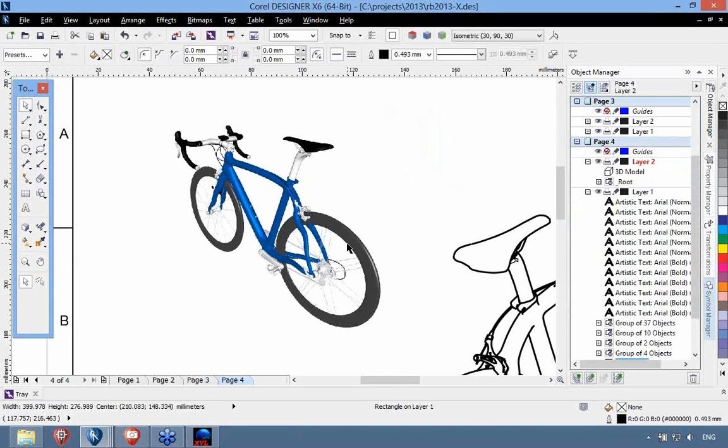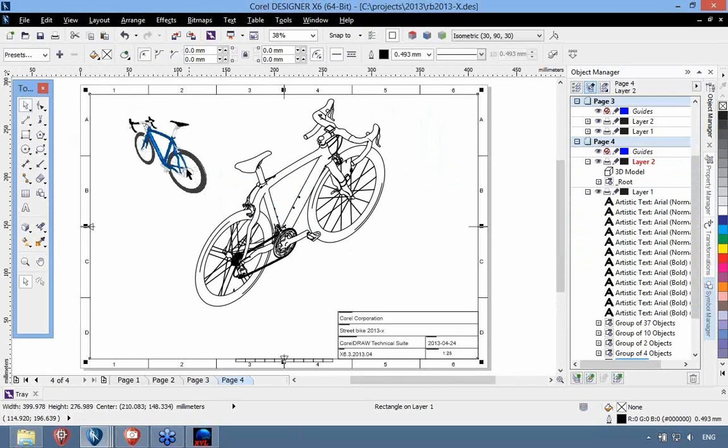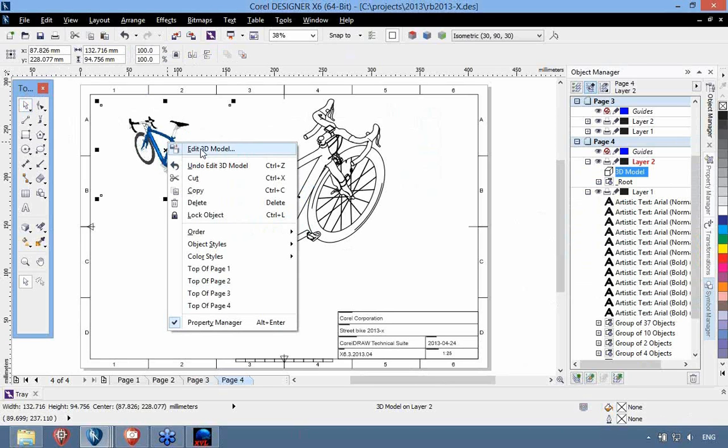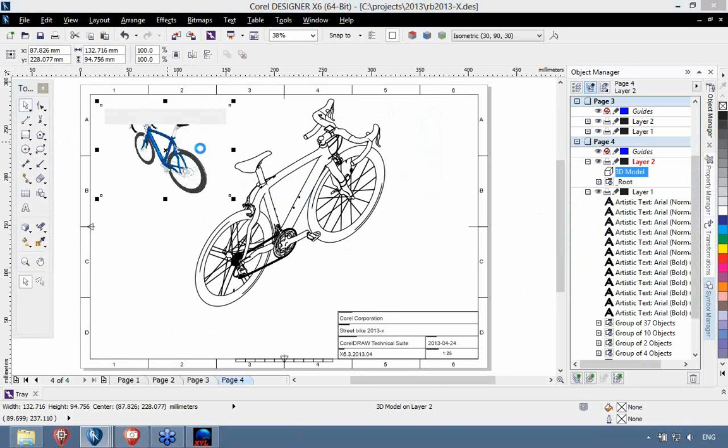So you see there's a high resolution preview image of that, and when I move to full screen again, that's part of my file. And if I get to updating that, for example, that 3D file has changed, I have new cameras in there that I can use here, or something has changed in the parts, then I can reload this reference XVL file, and at any time, right mouse click, edit 3D model, or double click into it.